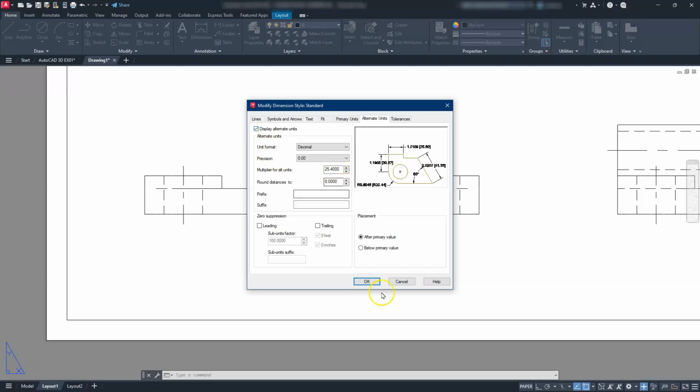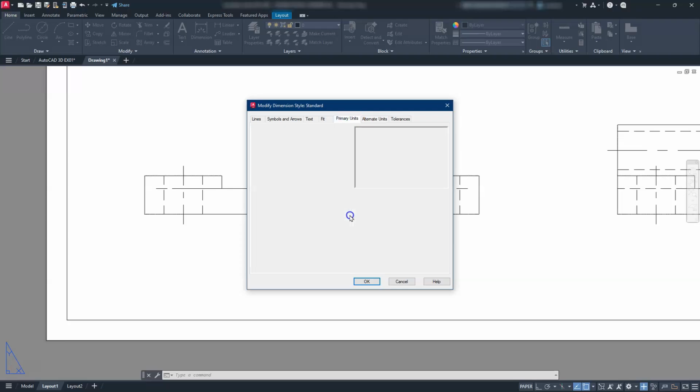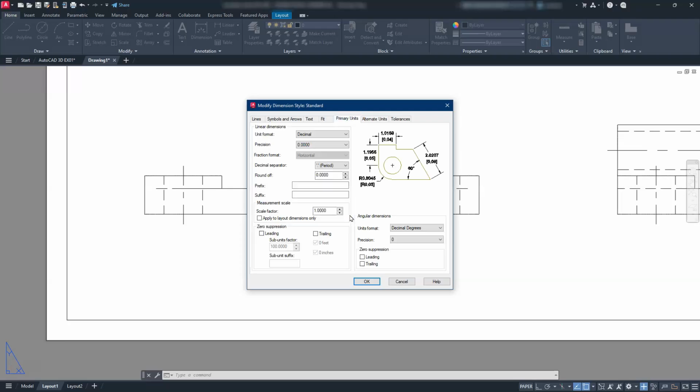All right. I'm going to put the value below it. So I got it underneath it. Next, I'm going to adjust this, right? I wish I could put in 1 divided by 25.4, but it doesn't work that way here. So I have to put in 10 divided by 25.4. It's the exact same thing. It's just some math numbers that we're playing with, right? But once I do that, now I'll jump over to the primary units. Everything should work fine at that one.